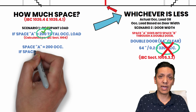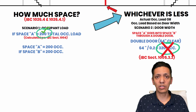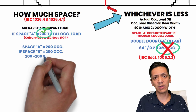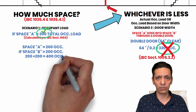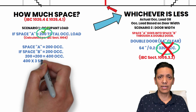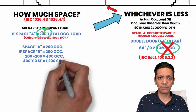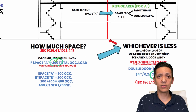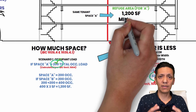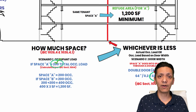And if space B has 200 occupants itself, then you have 200 occupants from space A plus 200 occupants from space B for a total of 400 occupants. Now all you have to do is take the number of occupants, which in this case is 400, and times it by 3 square feet, which gives you a total of 1,200 square feet. That is the size of the refuge area that you must provide within your horizontal exit.